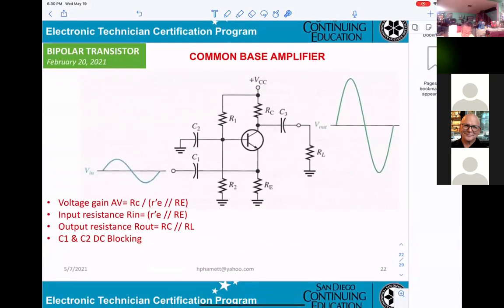So when you look into the circuitry, you see the input is now applied to the emitter and the output from the collector. So you get a capacitor here connected from the base to the ground. That will be telling you for AC, they will be ground. However, for the DC, they will be open. That's why you can get the DC voltage here.